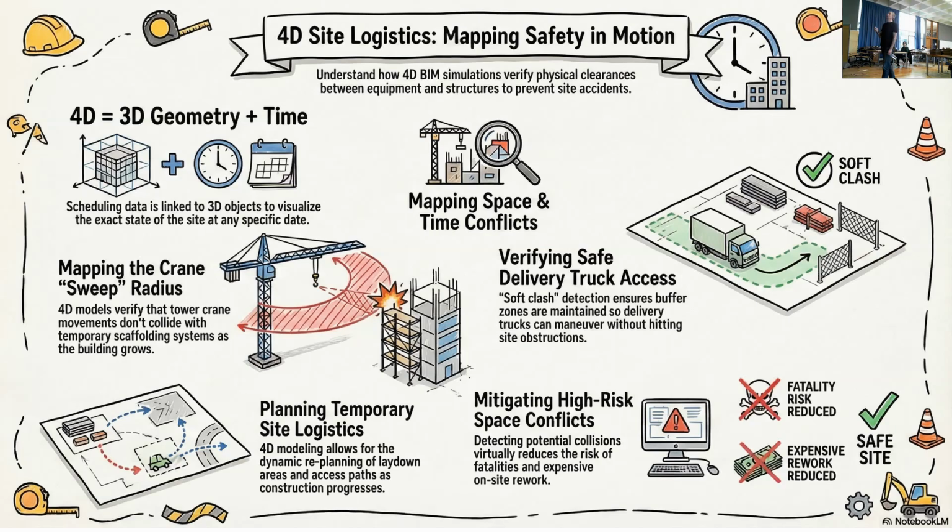So yeah, the sweeping space for a crane is very critical. You should be able to lift the crane up in time for the construction. Or if there's another building nearby which is already there, existing, tall, you have to take care of that. So here, how the trucks will come, where they will load, what kind of materials they're bringing, how often. Even in London, what they were doing was very interesting.